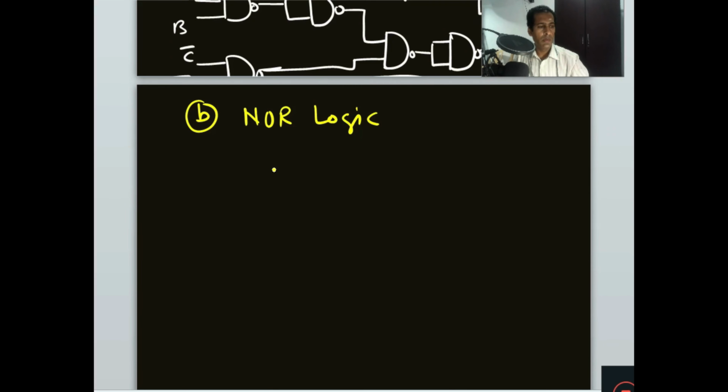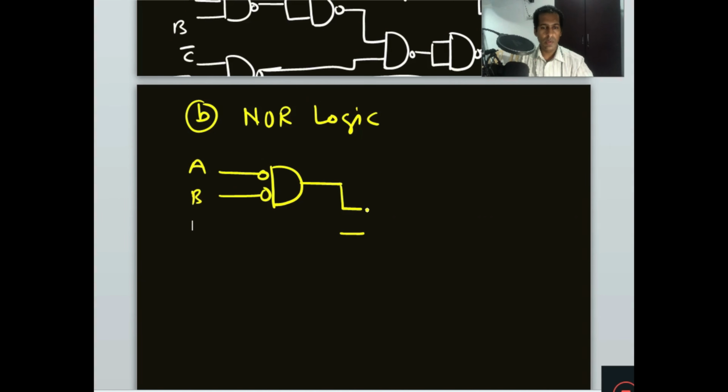First stage, we will put a circle at the output of each OR gate, and this time we will make AND gates into bubbled AND gates. The first input is A and B to AND, so we will make it a bubbled AND. The output of this is also connected to one AND gate, that also will become a bubbled AND gate.